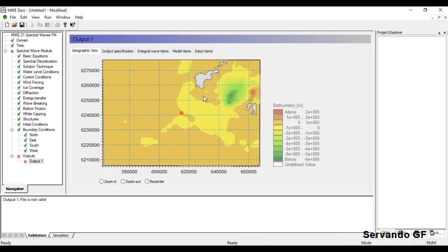I haven't spoken about the limitations of this model, but basically use this model to get wave heights around a shoreline, but not within basins of ports, harbors or marinas or anything. That model doesn't work for that. For those kinds of problems, you should use the Boussinesq model or some other models.